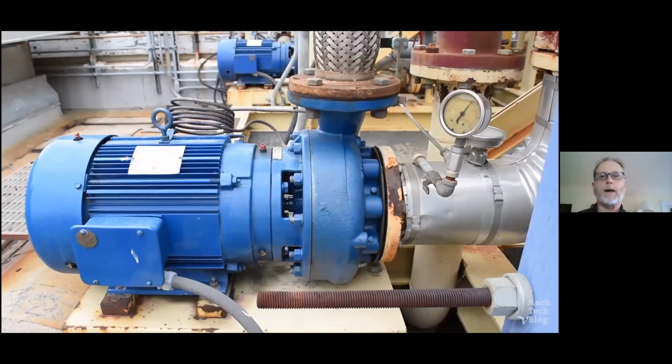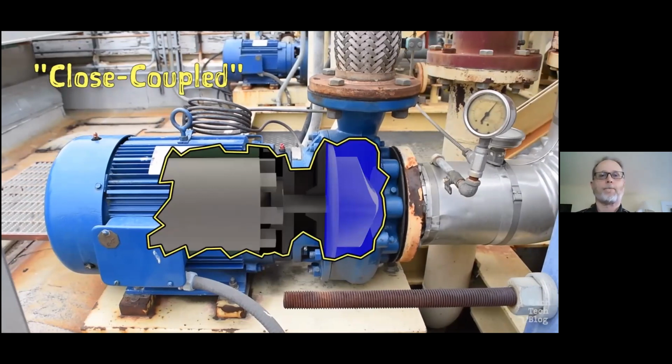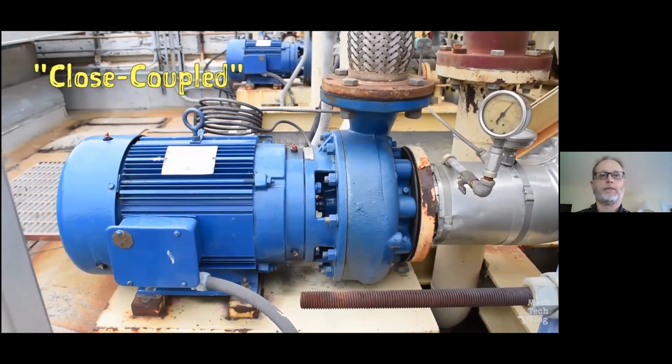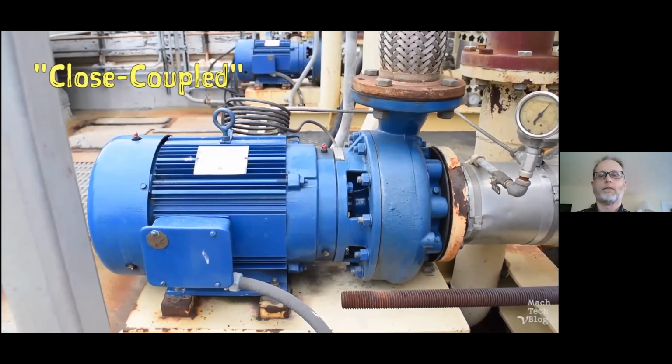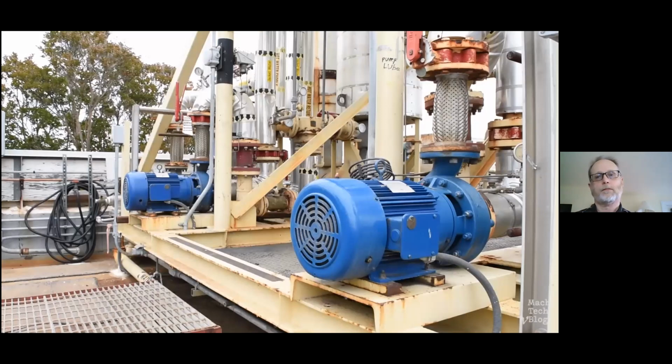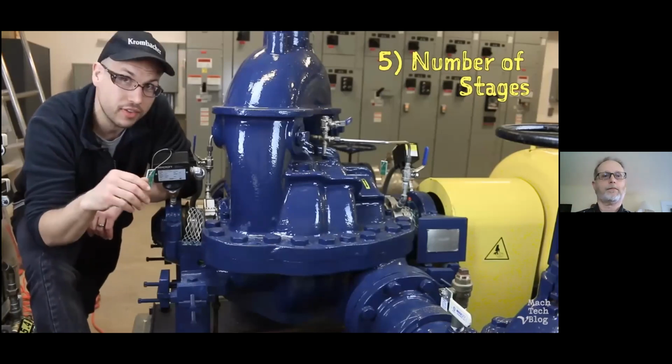A second option is the close coupled mounting method, in which the pump and its driver share a common shaft, with the impeller mounted overhung on one side of the driver shaft. In this case, there is no need for a coupling or any of the extra labor required to perform sensitive alignment procedures. However, since both the pump components and the driver components are supported on the same shaft just by the bearings in the driver, this mounting method is really only appropriate for small and medium-sized end suction pumps. Finally, a pump can be classified by how many stages it has.